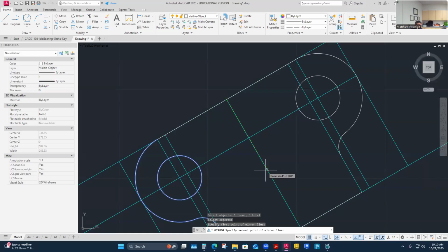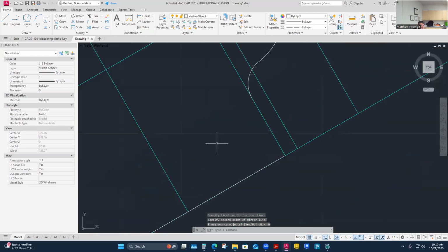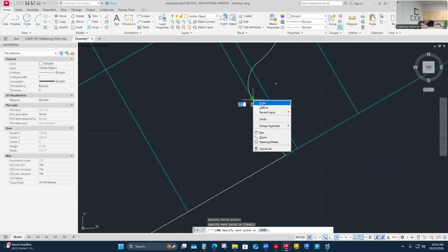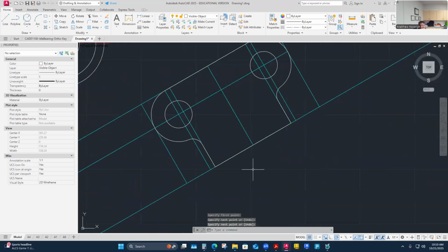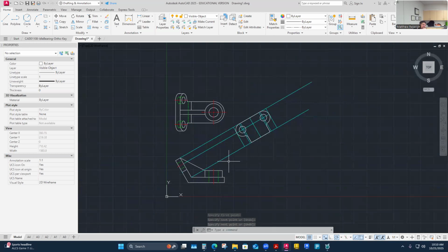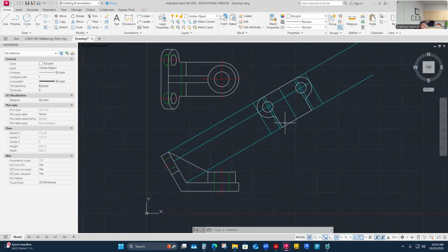The center line. I just have to finish a little bit of visible line work here. And then I should see the gusset. We would forego hidden line work if it cluttered my view. It's not that you can't include hidden line work, especially if it's helpful. Here I don't have any hidden line work to show, but I do have visible line work, and I would show that. So I'm going to show the gusset that I'm looking down on here.